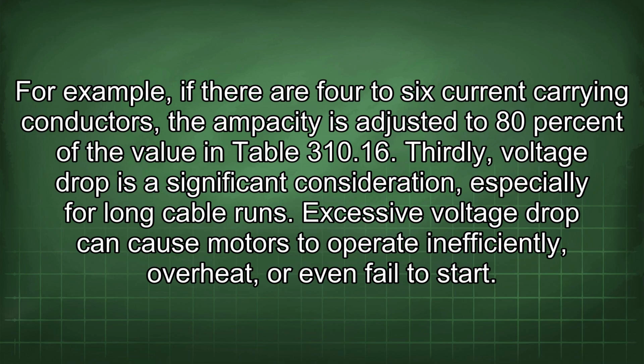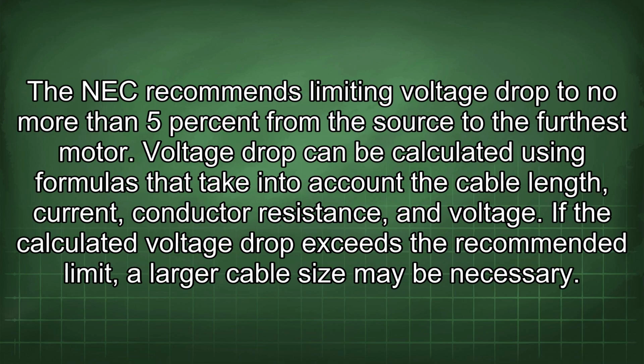in Table 310.16. Thirdly, voltage drop is a significant consideration, especially for long cable runs. Excessive voltage drop can cause motors to operate inefficiently, overheat, or even fail to start. The NEC recommends limiting voltage drop to no more than 5% from the source to the furthest motor. Voltage drop can be calculated using formulas that take into account the cable length, current, conductor resistance, and voltage. If the calculated voltage drop exceeds the recommended limit, a larger cable size may be necessary.